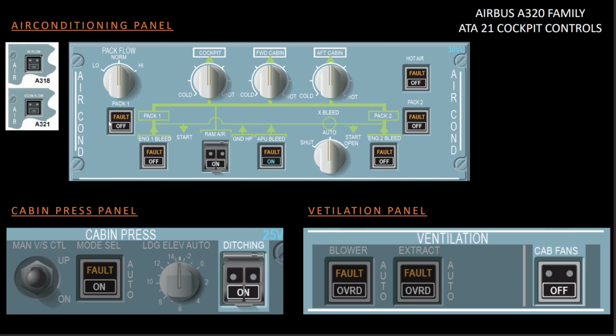So the flow control valve itself will have two closure modes. One would be manual closure, the other one would be automatic closure. What we discussed was the manual closure. That means you select it off with the push button, the flow control valve's on-off solenoid will get de-energized and the valve will close. Now I told you that there is another closure mode, which is an automatic closure mode. So what is automatic closure mode?